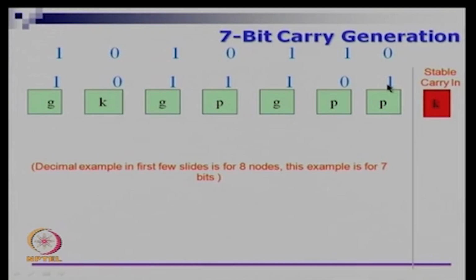So, let us say these are the two numbers that I want to add. I will calculate the sum and put it aside. Now I am going to look at only the parallel prefix stage. So 0 and 1 means propagate, 1 and 0 means propagate, 1 and 1 means generate, 0 and 1 means propagate, 1 1 is generate, 0 0 is kill, 1 1 is generate. I have the very first stage GPK. So this is before the prefix, this is the carry prefix that I wanted.